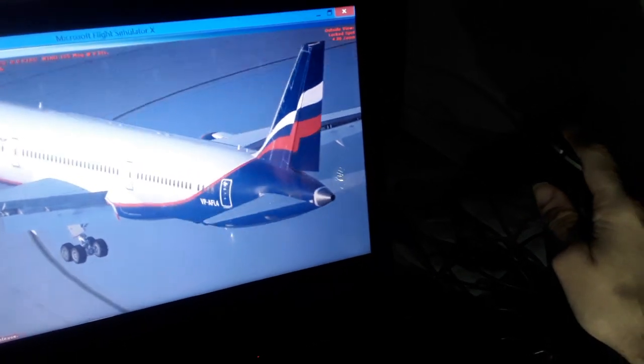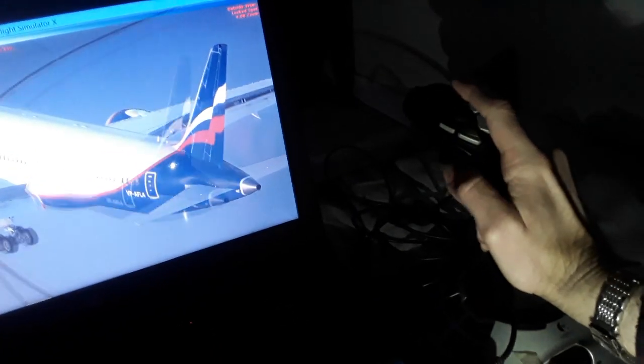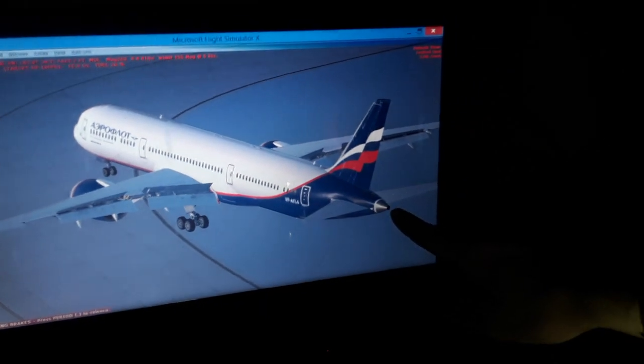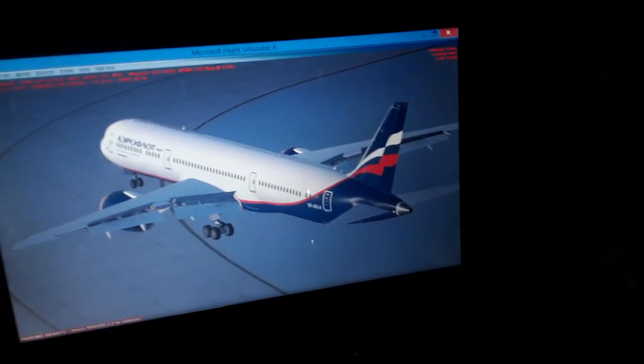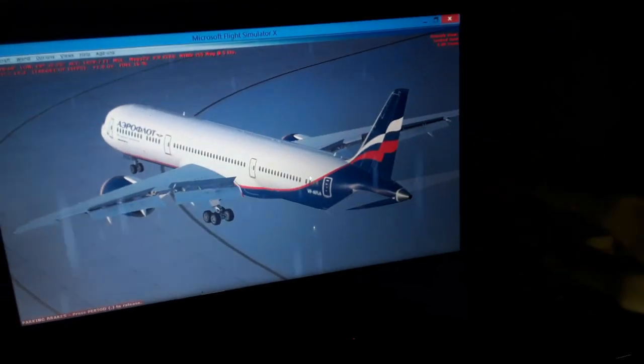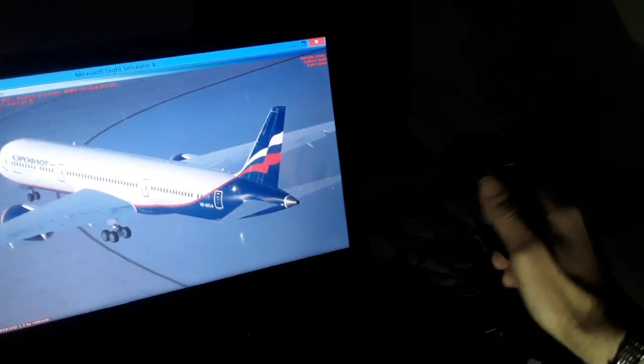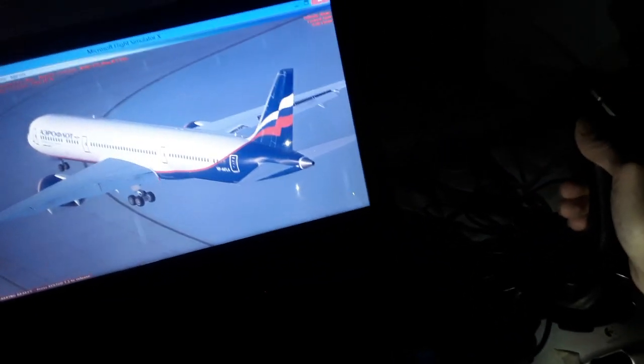Make turns in the flight. And also make turns around the longitudinal axis, as you can see. This is the longitudinal axis of the aircraft. It transverses again at the center of gravity, so you make the roll around the longitudinal axis using the roll spoilers, ailerons and flaperons.